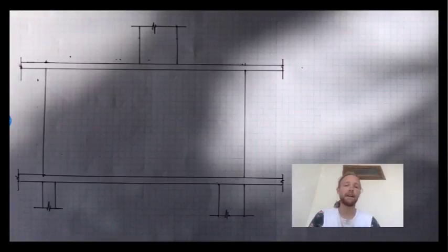So now you've designed the transfer, taking the load from one location to another. In this case, we're taking load from a column through to a floor, down to another two columns, due to probably an architectural constraint or something. Another thing is header beams in cores, which we haven't covered here, but you're sure to cover at some stage in your career. Now that it's been designed, the next important thing to consider is the panel breakup.